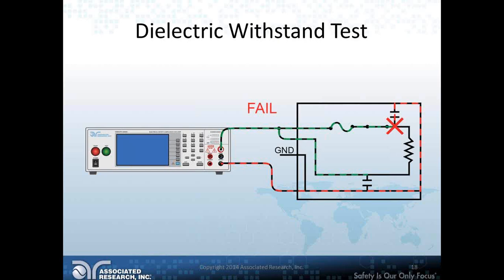And the maximum leakage current is dependent upon the test voltage. Therefore, the leakage current trip setting will vary depending upon the product being tested and the capacitance of that product. So capacitance plays a big role here. Highly capacitive products may exhibit a slightly different behavior.